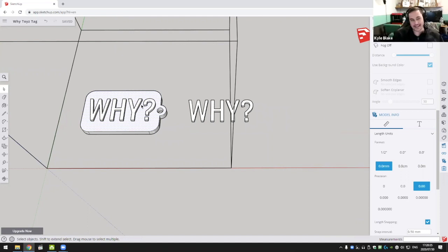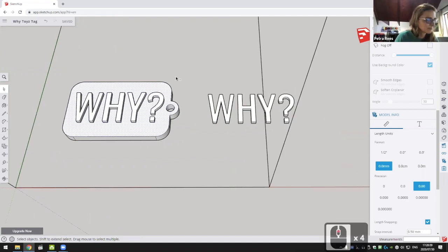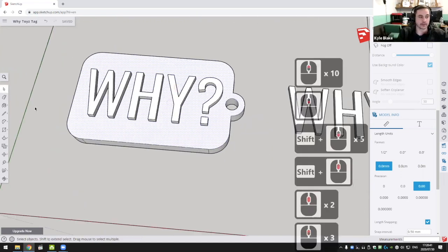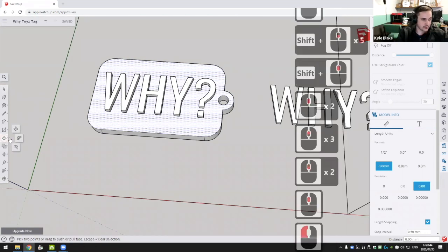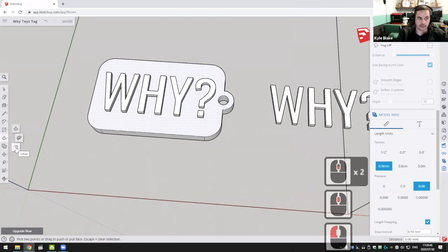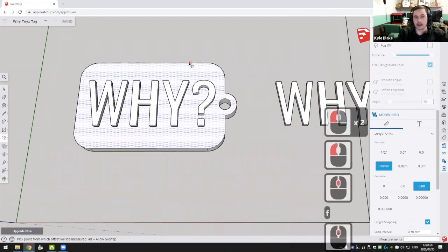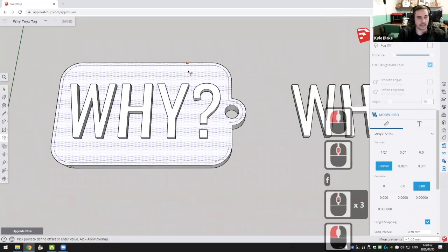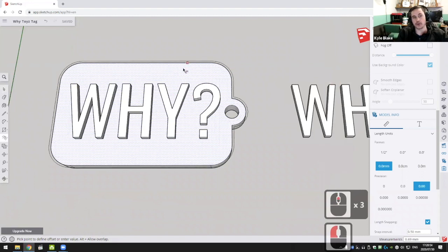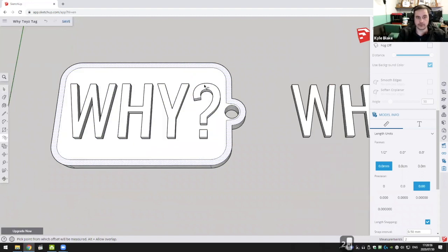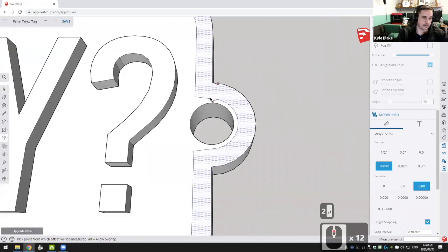Does everyone have a tag at least with some text? Yes. Okay, can I show you the offset tool to create a border for this? There is an offset tool underneath the push-pull. I think the shortcut's F for that. You can click on the edges and a line will pop up for how much you want to offset it. So I'm going to say 2. But then I end up with a junction here that doesn't look too great, because I know that the offset between my ring and the end was 2.5.